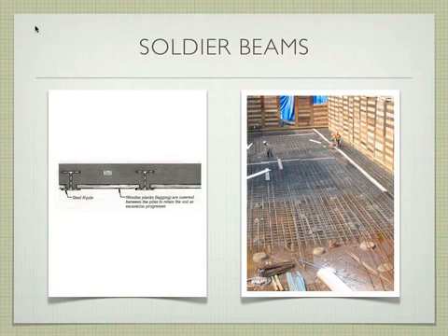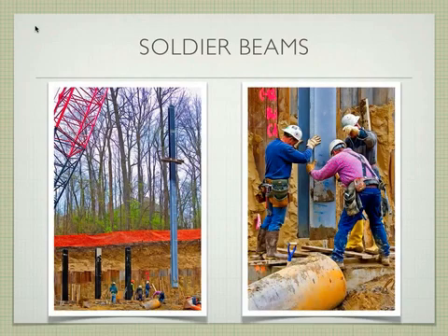So a soldier beam, and you've probably seen this type of excavation before as you're driving around. It's fairly common. What's going to happen is they're going to take a wide flange, an H-pile they call them, and they're going to drive it down into the soil. Let's see if I have another example. Perfect. So they're going to take this wide flange here, drive it down into the soil, like these have already been driven. Notice the size here. Here's the person, so it gives you some context for size.